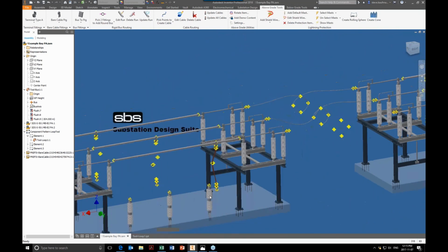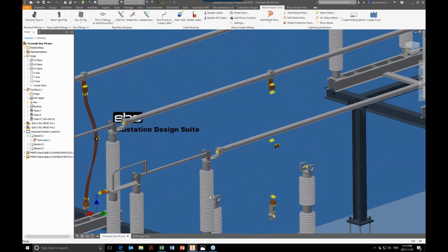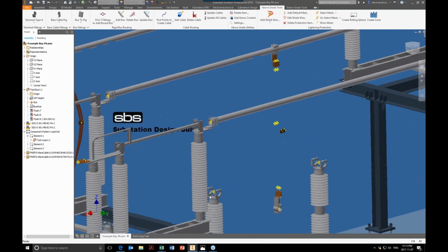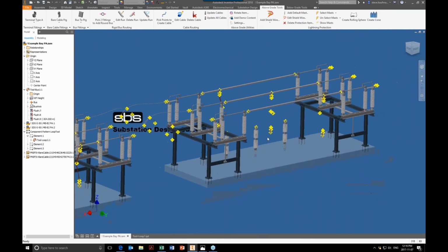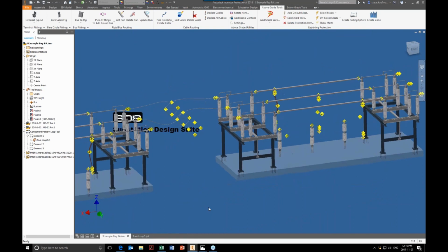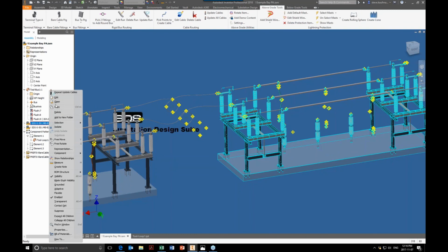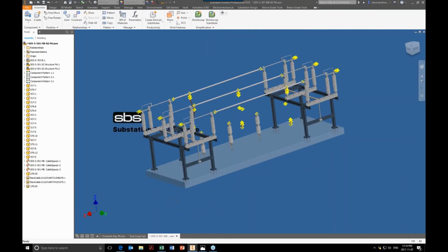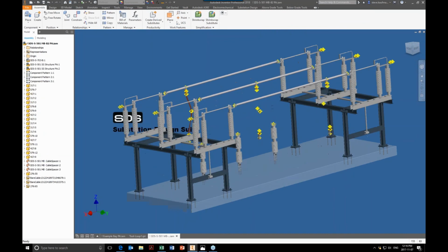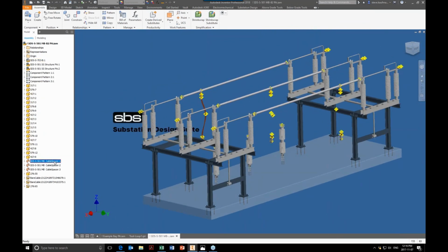Well, where else we may want to do that, like I said, is on these slack lines. I want to show a slack in here as well, right? So let's look at the cable loop tool or the cable slack tool in this case and on that assembly. So let's open up that assembly. Because I want it on islands, I want everything contained to the island as what we talked about in the substation modeling strategy. And let's look at that cable spacer.